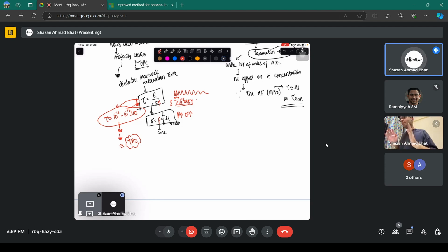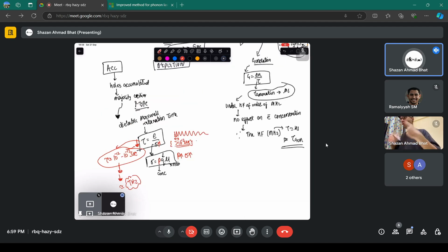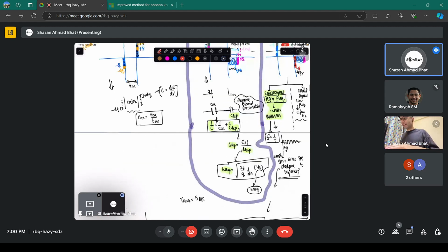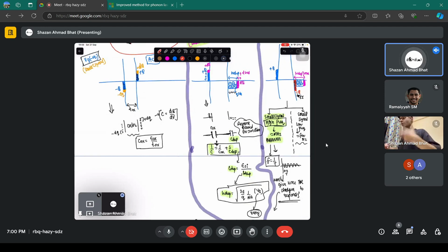That means unless your small signal is of the order of terahertz, it's not going to create any such non-ideal effects. The holes, these majority charges, are going to respond abruptly. And that's what happens in metals also. Even if you give a metal a very high frequency signal, electrons are going to respond quickly to that signal because there are free electrons present in that system.